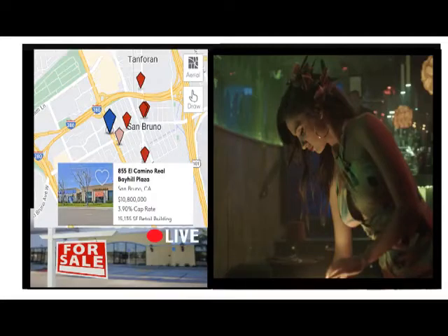Plywood sheathing is an excellent way to provide the bracing needed to protect a building in an earthquake. A sheet of plywood securely fastened to wall studs serves the same purpose as an X-shaped wall bracing system. Plywood sheathing allows a building to move with the movement of the earth yet keeps the structure intact so that it returns to its original shape.